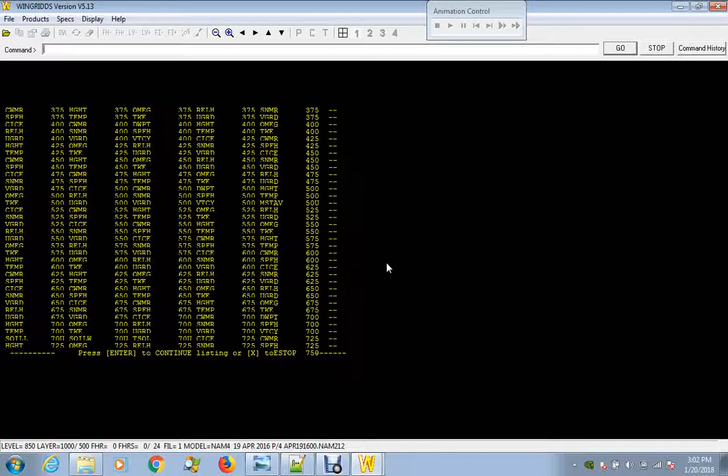Your latitude lines are rings around the pole spreading out towards the equator, and your longitude lines are like spokes in a wheel, radiating out away from the pole towards the equator. And so you have your least amount of distortion from about 60 degrees north latitude up towards the pole itself, up to 90 degrees, and then you have increasing distortion as you head away towards the equator. So those are your three main projections that are utilized for your gridded binary data.